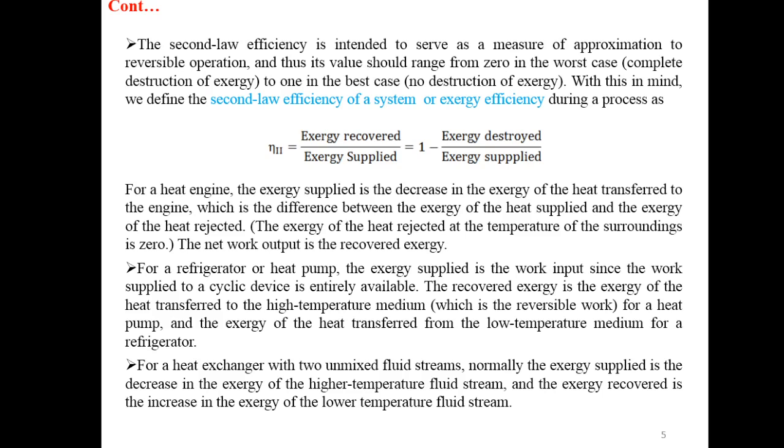For a refrigerator or heat pump, the exergy supplied is the work input, since the work supplied to a cyclic device is entirely available. The recovered exergy is the exergy of the heat transferred to the high temperature medium, which is the reversible work, for a heat pump, and the exergy of the heat transferred from the low temperature medium for a refrigerator.